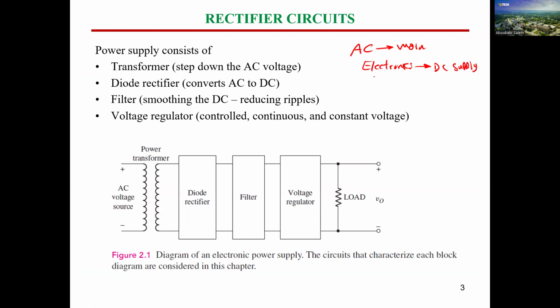Some types of electrical drives use DC motors, or even some types of AC motors need to be controlled by means of what's called back-to-back converters. So it includes a rectifier and an inverter. It's well known as inverter-based devices, like in air conditioners, for instance. So air conditioners also need a rectifier circuit.